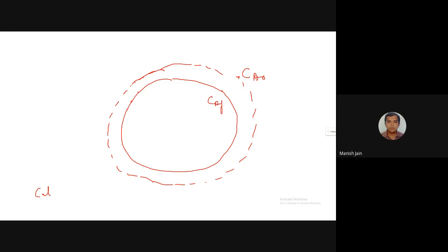So now you have to calculate the rate of diffusion of the component A. A is the reactant. Rate of diffusion of the reactant from the bulk to the catalyst surface. Okay, and suppose the reaction is A tends to B. This is a simple reaction, and then you have to calculate the diffusion of B from the catalyst surface to the bulk.